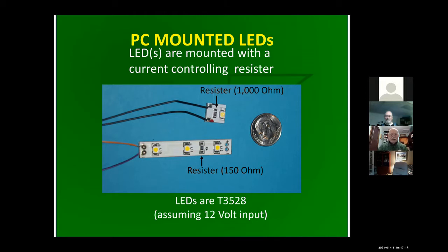If you're going to put it someplace where it's almost impossible to replace, maybe you won't want to use that. But they're pretty handy, and I have never had one burn out at this point. The resistor here is only 150. The reason for that is you have the 12 volts less 3, less another 3, less another 3, and so to control the flow, you only need a 150 ohm resistor. Okay.